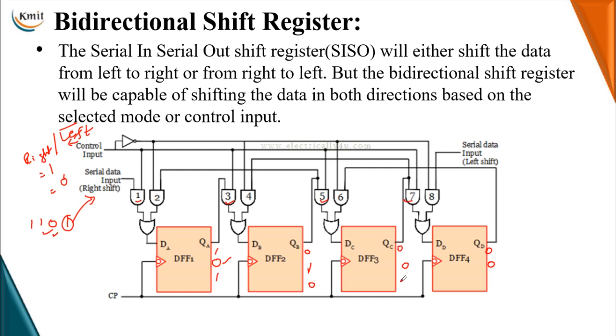Hence here you obtain a logical 1 as your input. So next here we obtain a logical 0. Next, at your fourth clock pulse, the last bit is entered into the first flip-flop, which is your 1 is entered onto the first flip-flop. This 1, the output of your first flip-flop, is shifted to the data flip-flop.